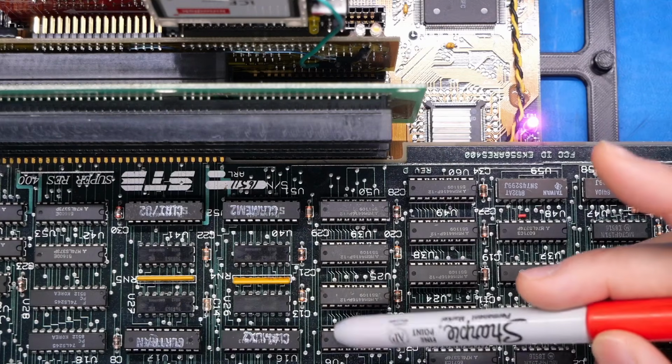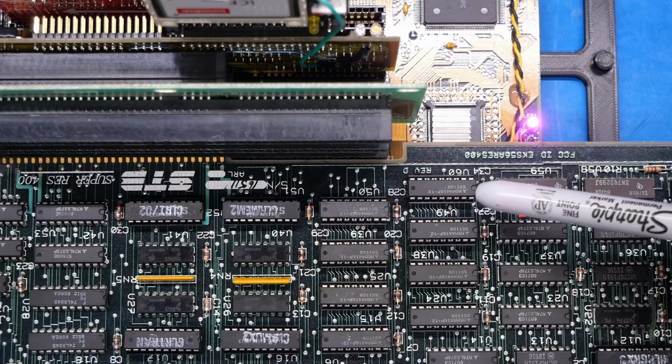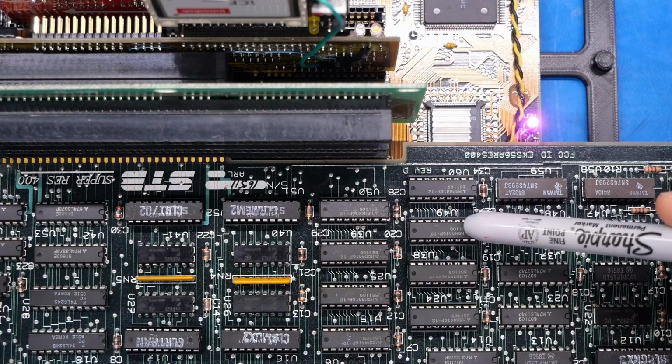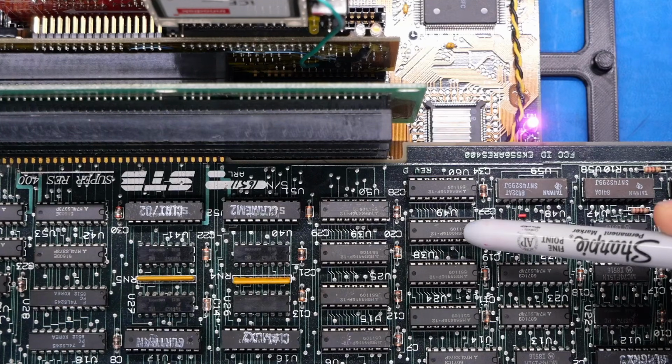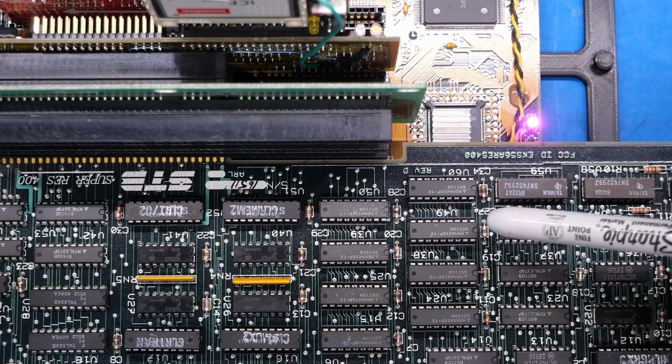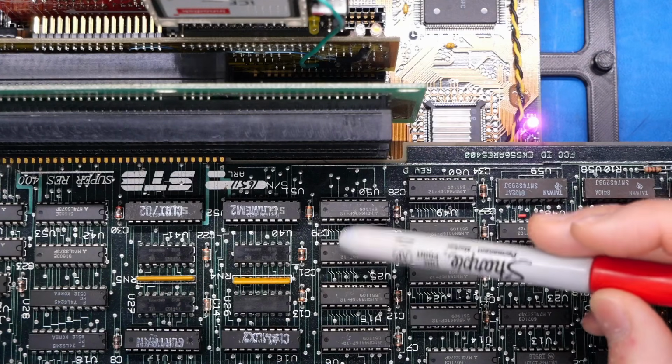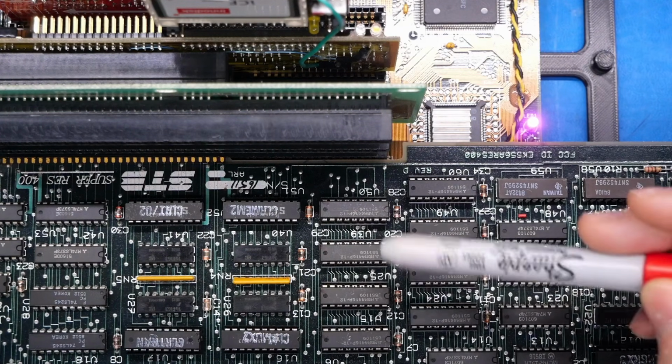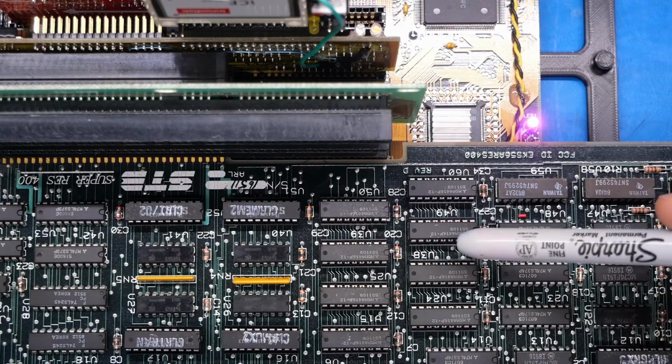And when you take a look at the card, these are the RAM chips, and these are 4416s. That means 2 of these chips make up 16K. Each one is 4 bits wide. And 2 of these is the original amount of memory that the CGA card has, and then these other ones are needed for the higher resolution or higher color graphics modes that this card does support.